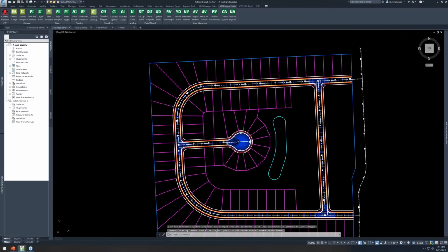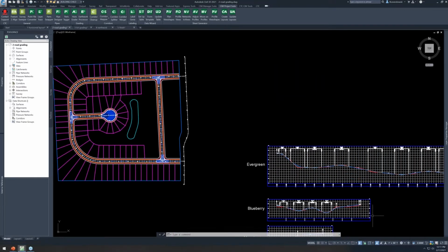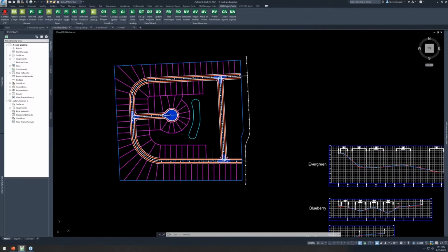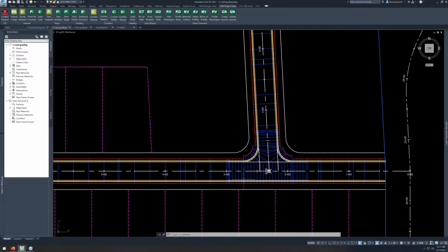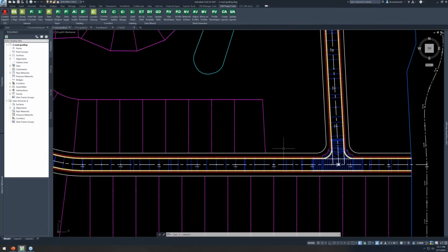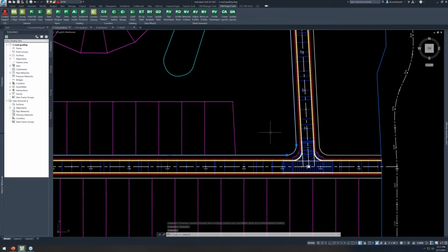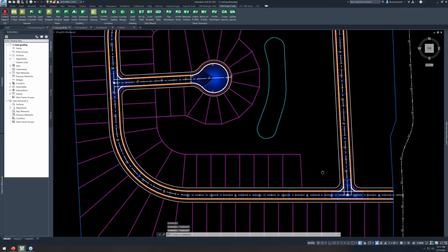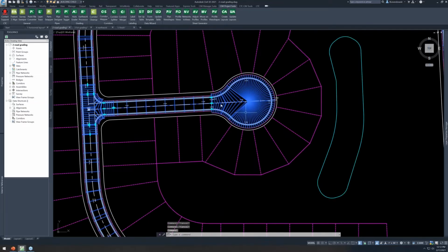And I've gone a few steps along. I've created some road profiles. I've used a corridor to start modeling my roadway. And one of the things I want to do is target this right-of-way geometry I have right here. And targeting in Civil 3D corridors becomes quite intensive, in fact. And so that's where one of these other tools come into play. Managing these targets becomes quite a bear.